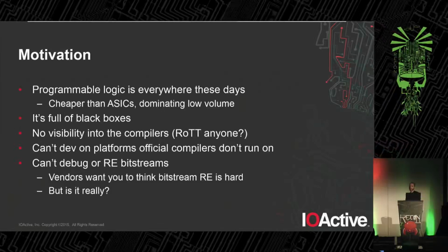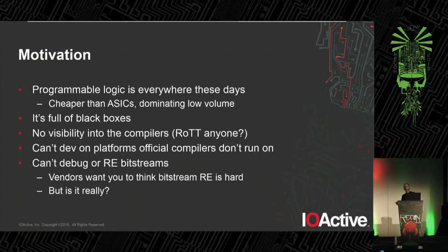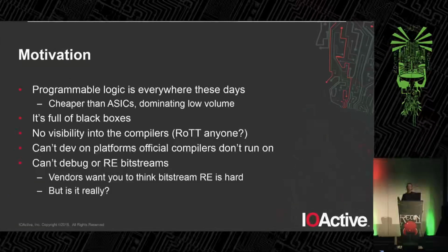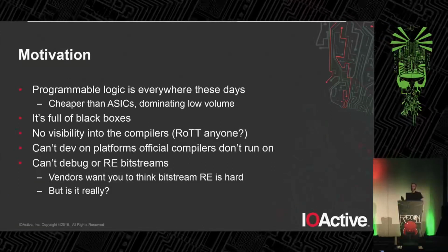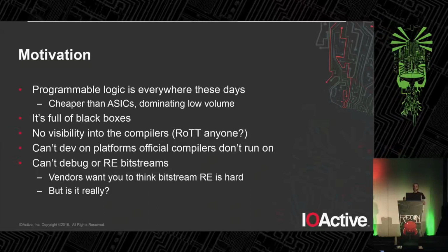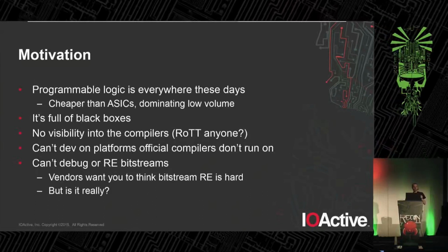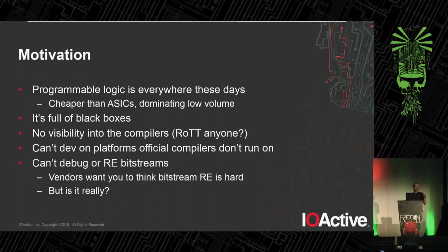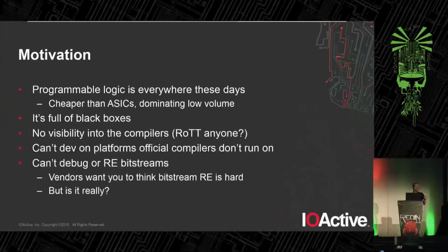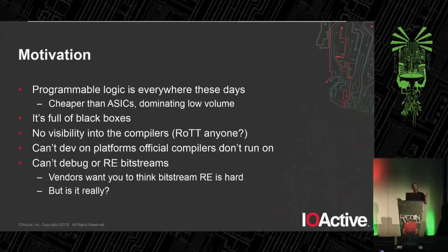And the problem is they're full of black boxes. Nobody really knows what happens when you compile your bit stream onto a device. You know, okay, well, we've got these lookup tables, we've got these RAM blocks, but what is actually going on underneath? How do I know that the RTL I gave the compiler is actually equivalent to what the actual device's behavior is? We don't know.